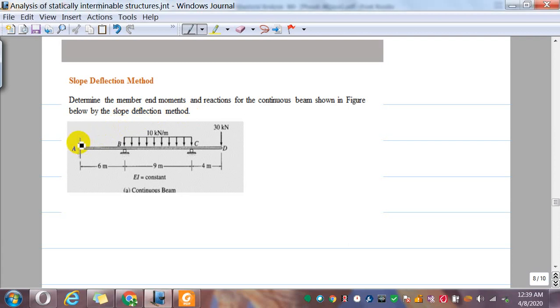As you can see, here you have a fixed support at A, a roller at B, and a roller at C. So if you consider the number of unknown reactions, here you have 3 reactions at the fixed support, here 4, 5. So R is greater than 3, which means you cannot statically determine the external reactions.